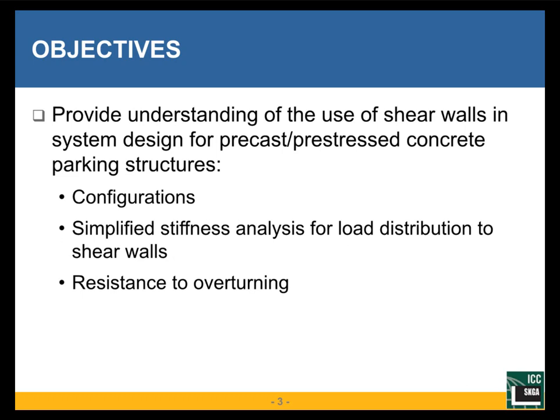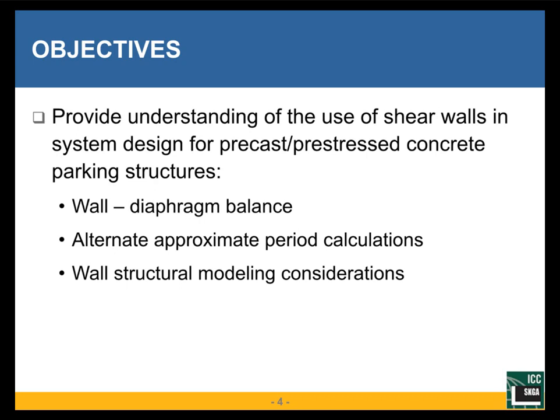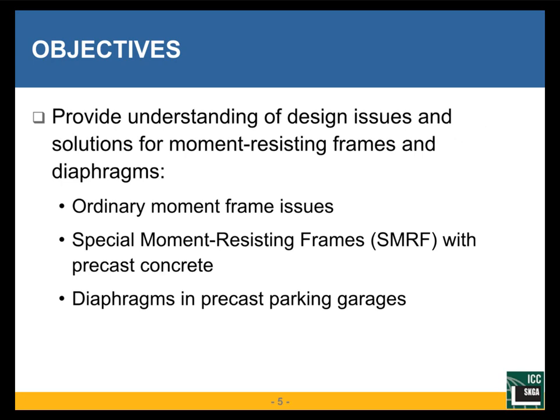We will provide an understanding of the use of shear walls in system design for precast prestressed concrete parking structures, including their configurations, some simplified stiffness analysis for load distribution, and considerations of resistance to overturning. We're going to provide an understanding of the use of shear walls in the design of structures with a consideration of wall diaphragm balance, the alternative approximate period calculations, and wall structural modeling considerations.